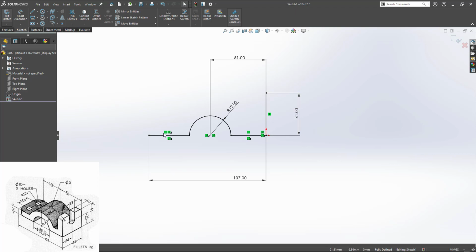Now I would like to offset this all. So you can just press the S key. You can select the offset from here, or else here also you have it. So anything, you can do it. Select chain is active, so you can select everything in one shot. If you uncheck this, a click will work out. The dimension you can see in the picture is 11. You can try reversing it. Yep, this is what I need. Simply click on the green check.